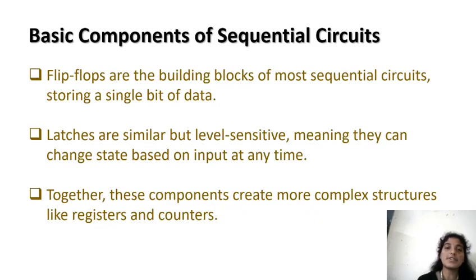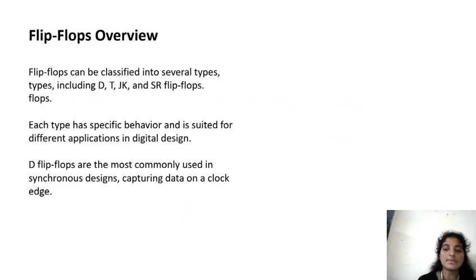Basic components of sequential circuits. Flip-flops are building blocks of most sequential circuits, storing a single bit of data. Latches are similar but level sensitive, meaning they can change state based on input at any time. Together, these components create more complex structures like registers and counters.